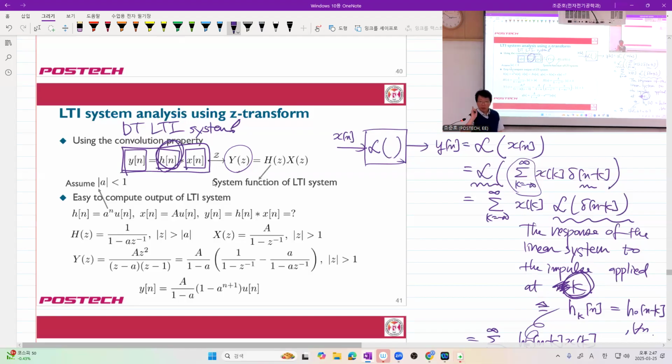the mapping expression for this Z transform is the product of the mapping rules. Of course, we have to be careful about what? The region of convergence. If z is in the intersection of the ROC of H and the ROC of X, then this is guaranteed. But for some z outside the intersection, we still have this Y of z converging. Why? Thanks to pole-zero cancellations. Right? So here go some cases, but be careful. Not every, but some.